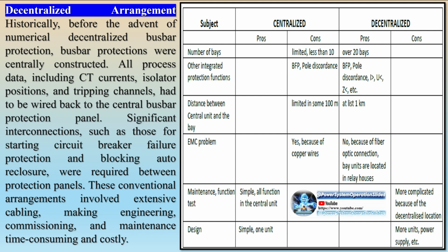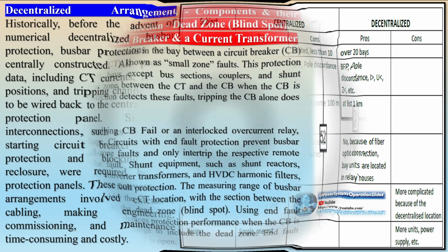This includes verifying the accuracy of input data acquisition and the functionality of internal protection components. The primary busbar protection fault supervision functions include detecting faulty current measurements, disconnector position errors, and internal component failures. These supervision functions continuously operate to prevent false tripping and ensure reliable busbar protection.